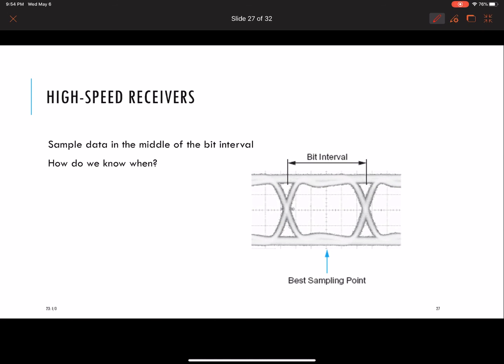trigger the scope off of your input data, okay? And since your input data is random, you're not triggering off the clock of the data, you're actually triggering off the data itself. Because it's random and you put your scope in persistence mode, it's putting these waveforms on top of each other. You basically get an averaging of all the types of bit conditions on top of each other. Of all types: zeros followed by 2 ones, 0 followed by 3 ones, 0, 1, 0.